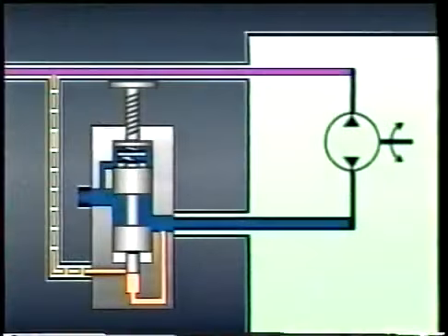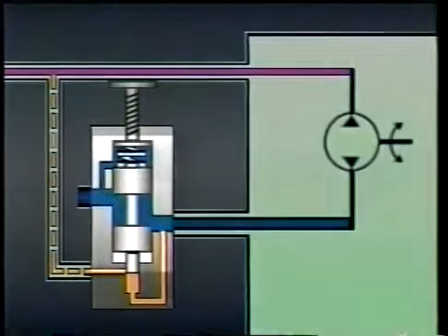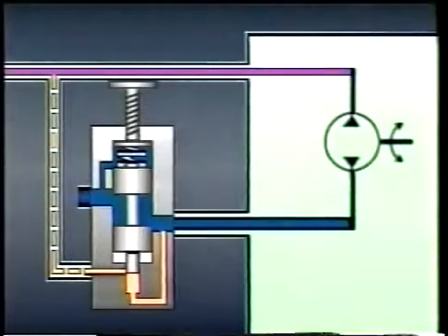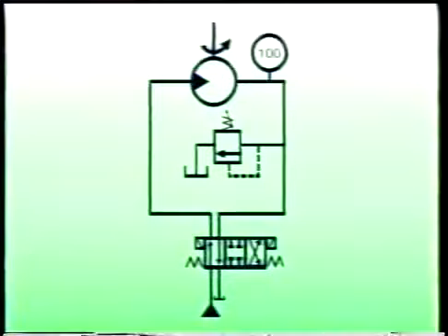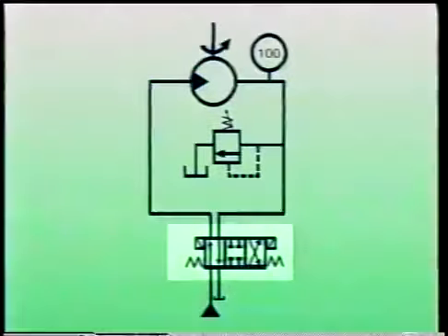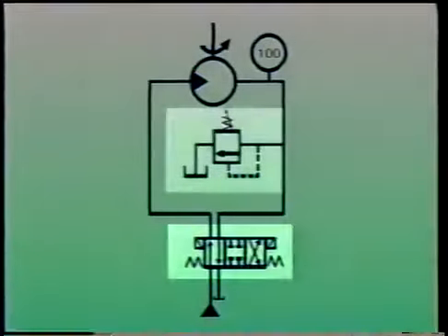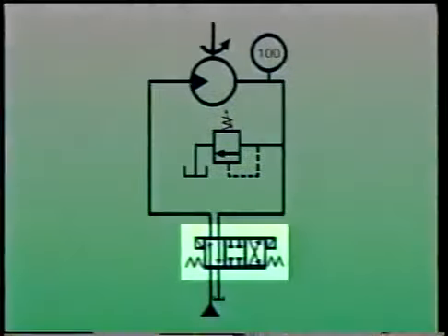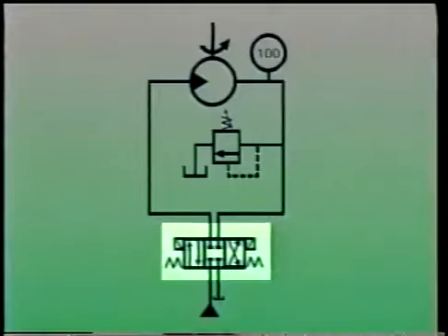A brake valve can automatically apply just enough back pressure to keep a load from running away with the motor, but still allow the motor to develop its full torque. Braking can also be achieved on demand by using a directional control valve and a standard relief valve. To brake the motor, the directional control valve is shifted to its center position.